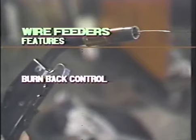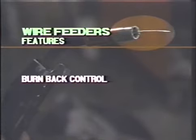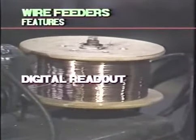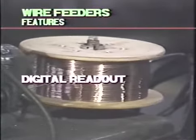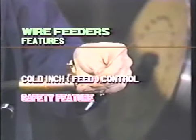Burn back control eliminates the need to keep trimming the wire for the correct stick-out length. Correct stick-out ensures minimum spatter at the weld starts. For consistent amperage, a digital wire feed speed readout enables the operator to obtain consistent results. An important safety feature is a cold feed control, which feeds wire through the torch without connecting the current.